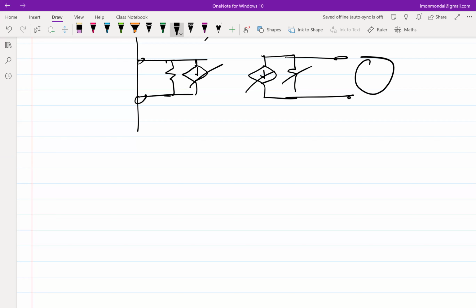But obviously, it sometimes becomes clumsy to change test benches, apply V, find out the ratio and all. So there's a good S parameter analysis built into the software, right? If you use SP analysis and run SP, that is going to give you the impedances also, Z11, Y11, everything it will plot. You just have to ensure that you are doing the right thing. As long as you do that, it should be fine. That is one of the reasons I wanted to talk about this.